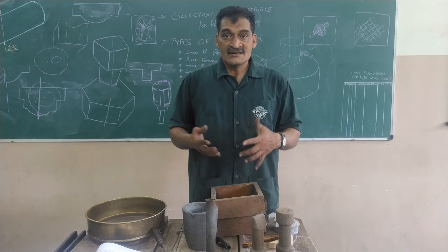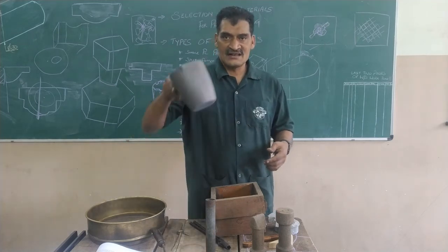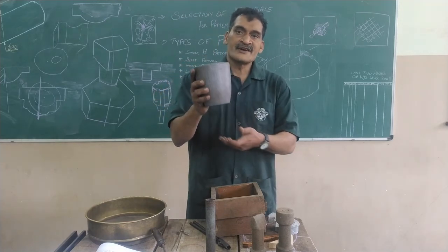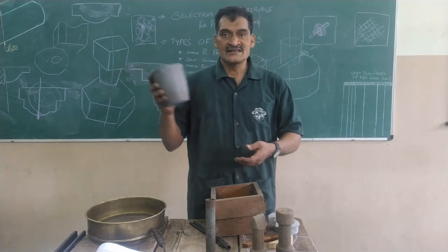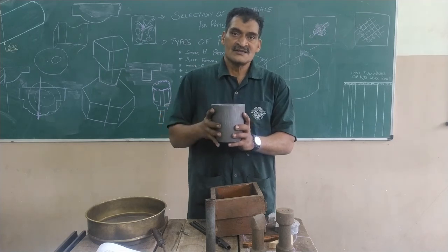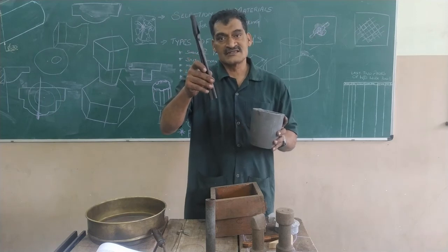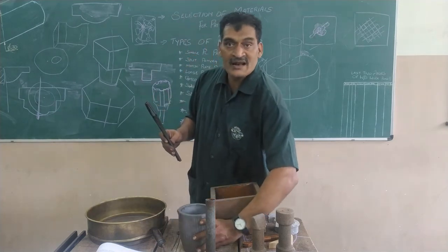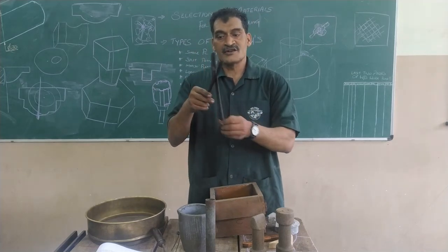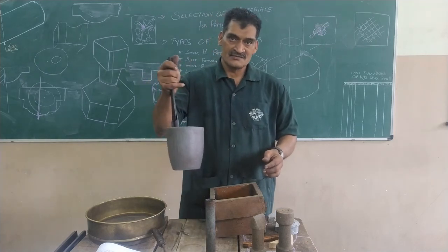Besides the apron, when we deal with hot work, we will be using tools like these. This is called the crucible. This is made of graphite. This is used for heating the metal. So the metal will be heated within. When we deal with this, we require tongs. We directly cannot hold it with gloves either. We use tongs like these for holding the crucible while pouring it.